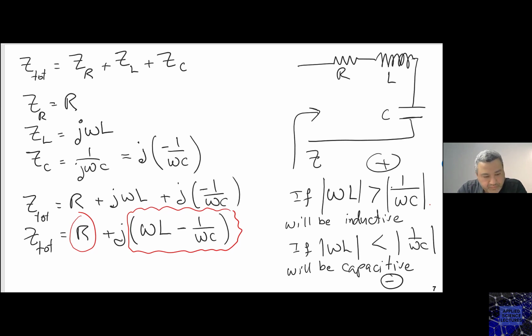So again, does this relate to the tank circuit? Because when you have the capacitor and inductor in parallel, this is what you need to create alternating current. And when the two reactances equal each other, that's the resonant frequency. Well, that's the thing, it depends. If they're in parallel, they're going to create an infinite impedance, right?